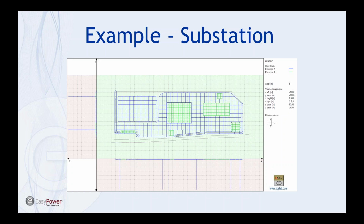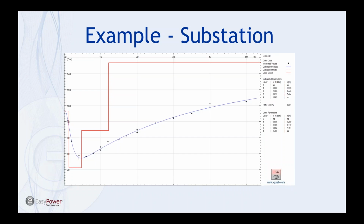And the green in the foundations represents the actual rebar inside the foundation. The foundations aren't generally used as a main grounding conductor, but in a robust grid like this, they can be connected to the grid. And so this is sort of an example of what you might upload from a DXF file into a grounding program.